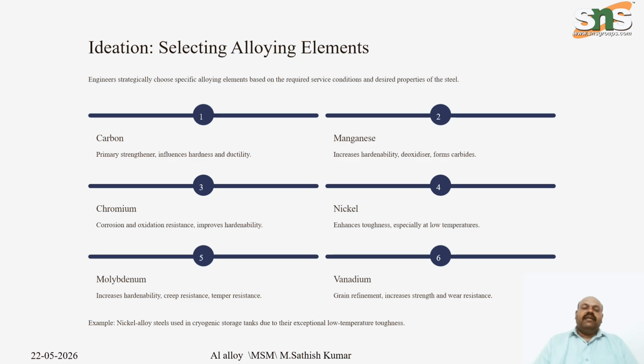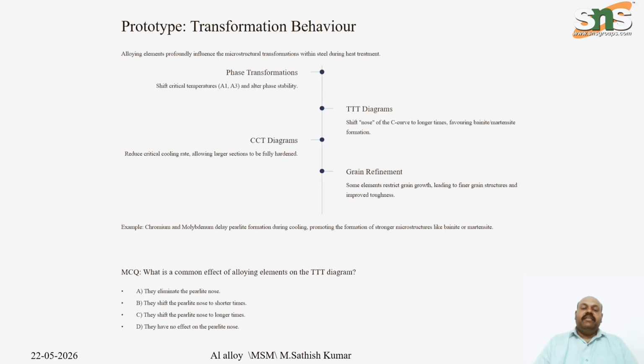Chromium provides corrosion and oxidation resistance and improves hardenability. Nickel enhances toughness, especially at low temperature. Molybdenum will help to maintain red hot hardness.